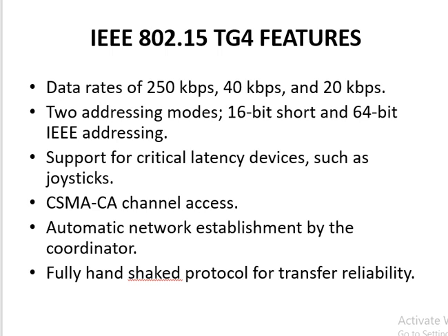Data rates of 250 kbps, 40 kbps, and 20 kbps. Two addressing modes, 16-bit short and 64-bit IEEE addressing. Support for critical latency devices such as joysticks and CSMA/CA channel access. It also enables automatic network establishment by the coordinator, and a fully handshaked protocol for transfer reliability.